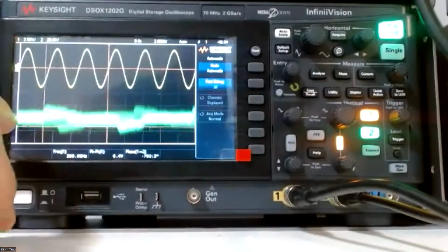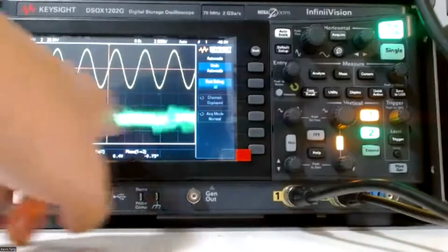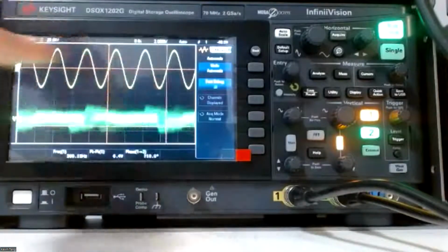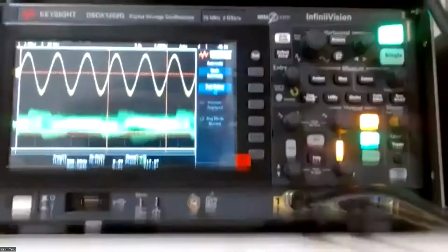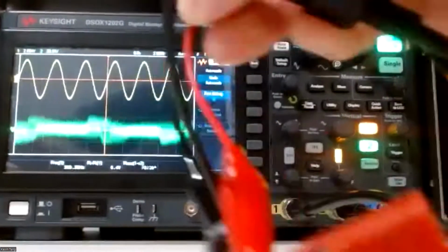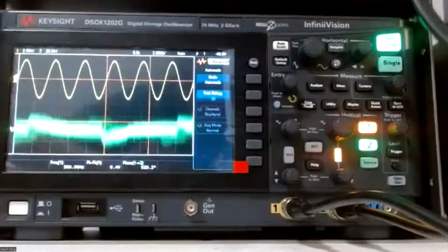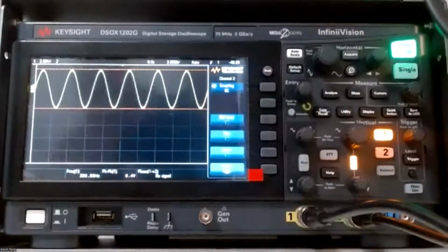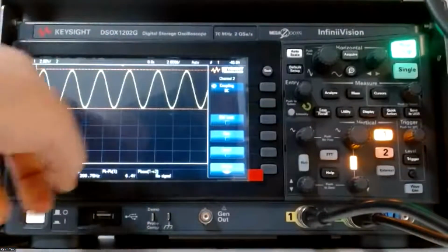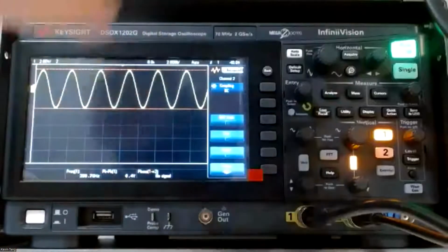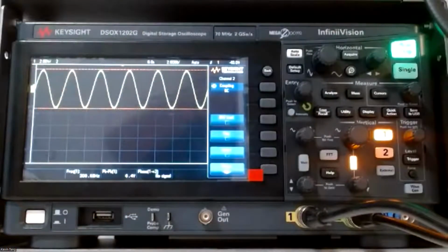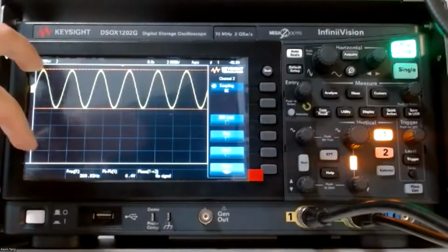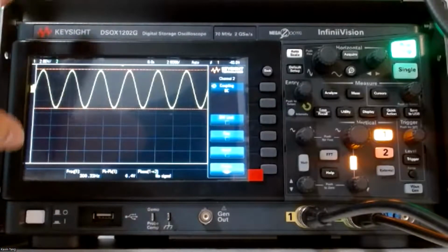Now you see the channel 2, the green wave is pretty messy because obviously we don't have a channel 2 input. I only connected this to channel 1, nothing to do with channel 2. What you can do is turn off channel 2, so just let channel 2 go away. Now you have this wave sitting on the top. Remember, it's a little bit different than what you have on Multisim, because Multisim starts with the middle. This is how the scope always does, it splits the two waves.